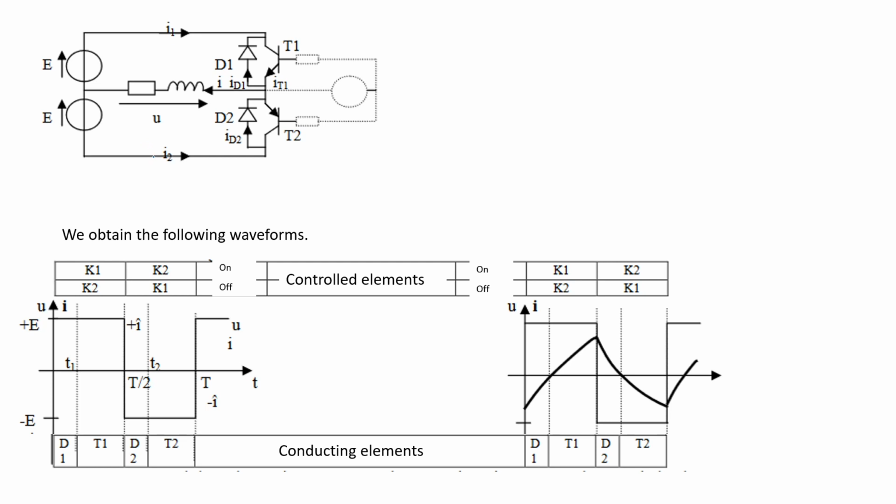Okay, so here is inverter with L filter, only inductor. And then the switch function we apply for the switch to be on and off in this way, so that we can have voltage across the terminal here, U, to be like this, and then the current I. So if we switch very fast, or we use very large L, then the waveform of the current would be like this, because this one is just first order.